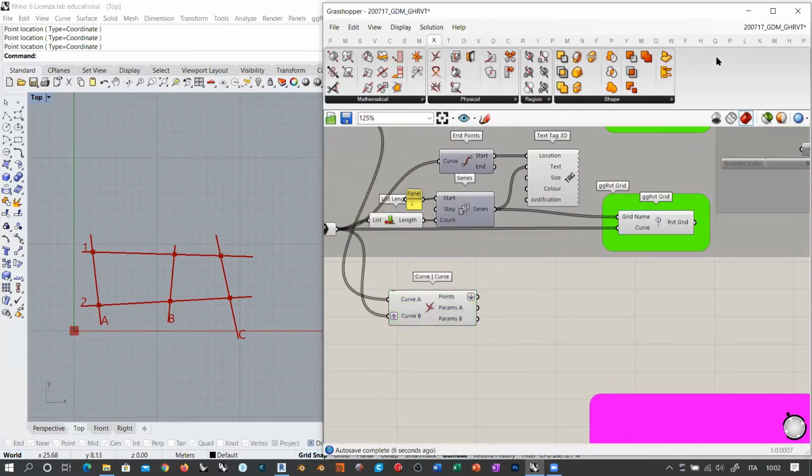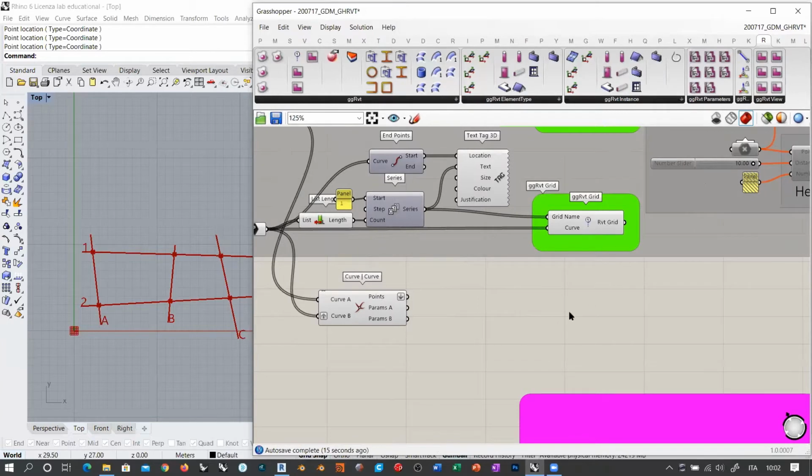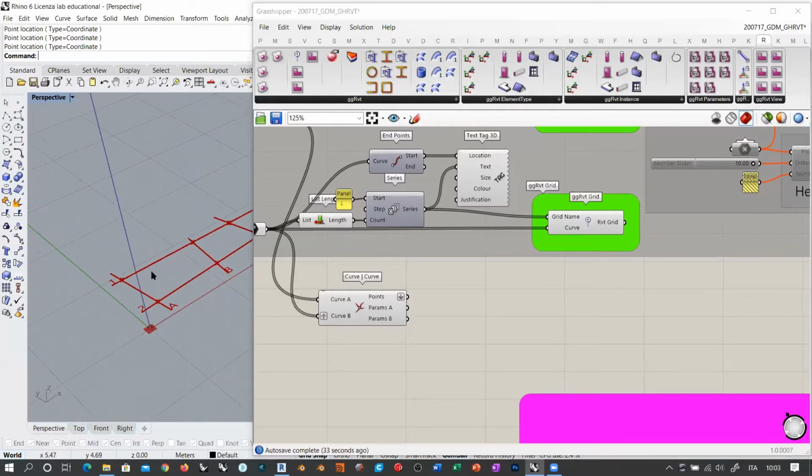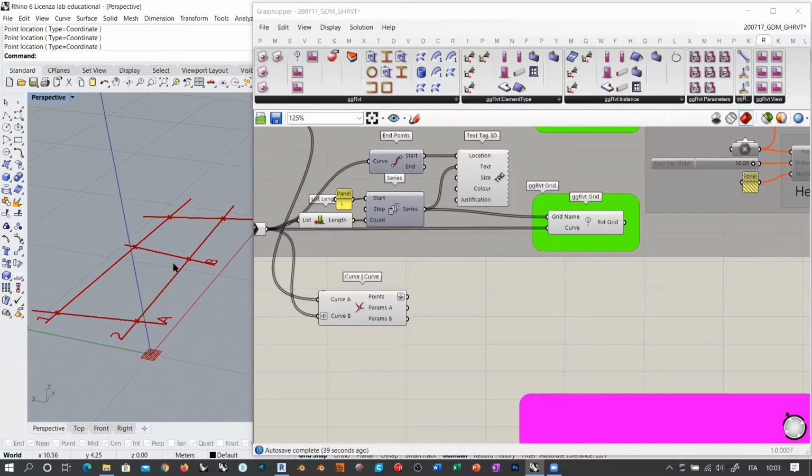So what we want to do next is go into our, let's see if it's visible. No, it's no longer visible. Our Revit toolbar, and start considering placing columns, physical columns at the intersection of these grid lines. I suggest you start from the end, at least at the beginning. You start with the end nodes, because it's easier to populate or to feed those nodes with all the necessary parameters that Revit asks for.